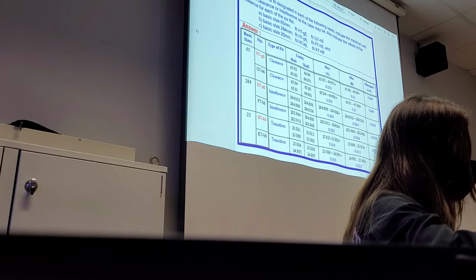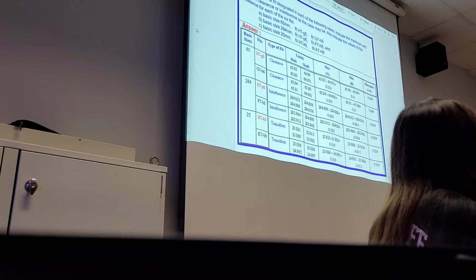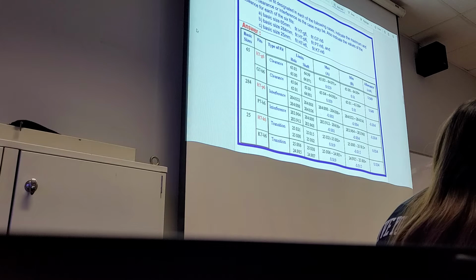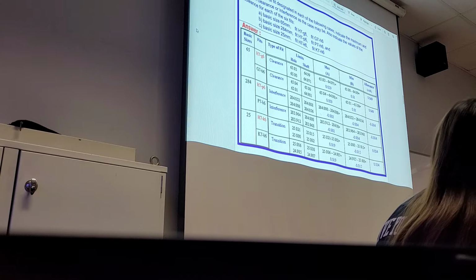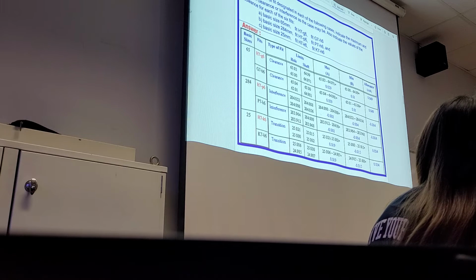So for these specifications, you can see here there are so many different specifications. Just to give you examples, all these are chosen fitting specifications from the tables. For example, basic size 65 H7 G6. Looking at this specification, I know this is a clearance fit. If you're not so sure, you have to refer to the table. Remember, in the table we write down that H7 G6 is a clearance.